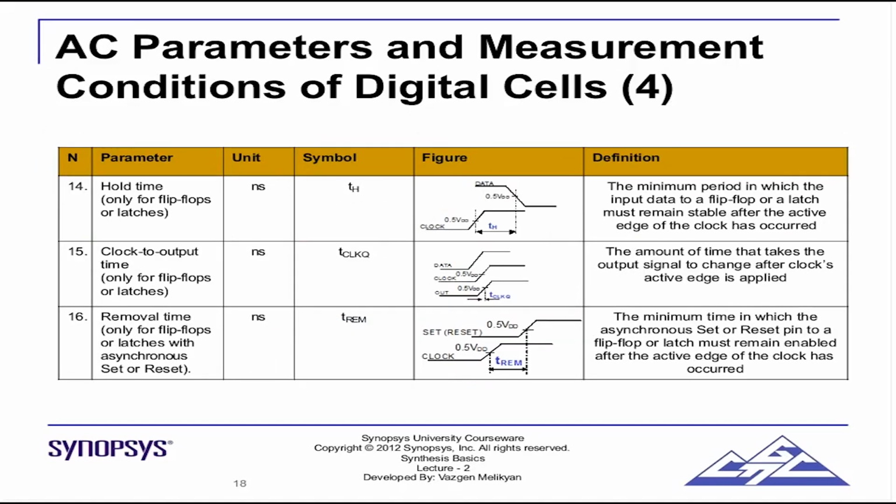Similarly, we have hold time. Now this is a time, so data should change only after TH. Again, a minimum amount of time. So if you notice that, take a clock signal. Now before and after, there are two limits. The time before is the setup time, and the time after is the hold time. This is setup and this is hold.